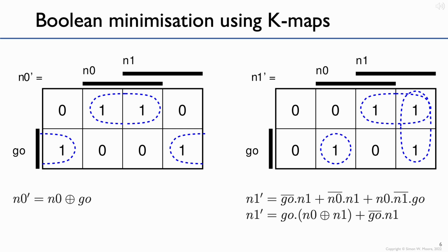In the N1 case, it's slightly more complicated, and you will have done Boolean minimisation by basically drawing sausages around common state. In this case we've drawn the sausages around the 1s, and we can see where the don't care terms are, or where we don't care about particular input variables.